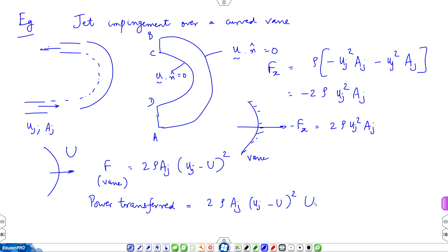You will study that it is possible to convert potential energy into kinetic energy. This is an everyday observation that an object kept here, if I leave it, then it accelerates, your potential energy gets converted to kinetic energy. So, similarly, a body of water kept at some elevation, it could be a reservoir at some altitude, and then you have a tube at the base, and then water will just start gushing out, with the gravitational potential getting converted to kinetic energy. So, there are natural reservoirs, so it rains and you have collected water over there, and then you can use its gravitational potential, convert it into kinetic energy and produce a jet of water.